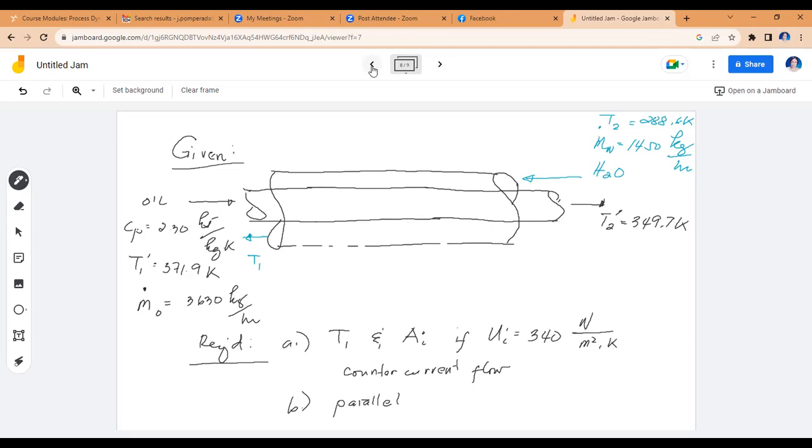It's not only the delta T log min that we can use in this case, but we have also other ways of determining that. We can use effectiveness, the heat exchanger effectiveness, but that's under a different topic. So we'll just discuss the topic that we have now. Okay, so question, are all 4 temperatures for the delta T log min complete? Of course, your answer will be no, because in the first place, you're asked for the outlet temperature of your cooling water. So since it's not complete, the next question is there a way for you to complete it? Using concepts of heat transfer, would you be able to determine the T sub 1 in this case, as we have labeled it or represented it?